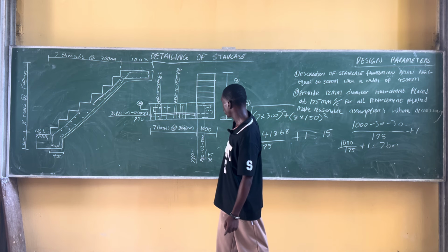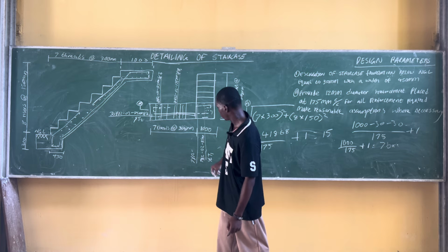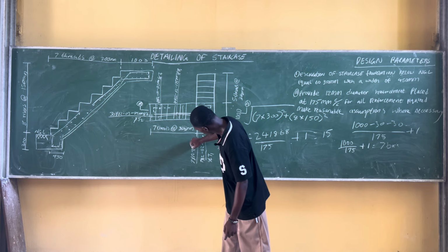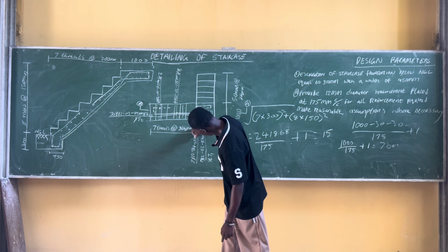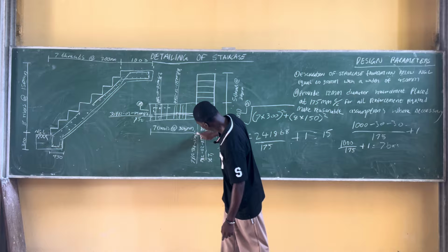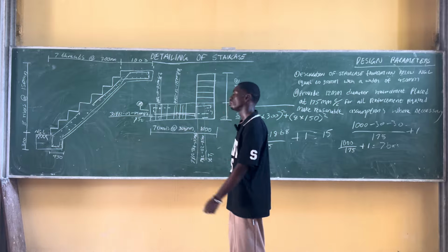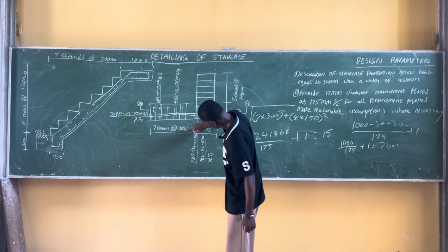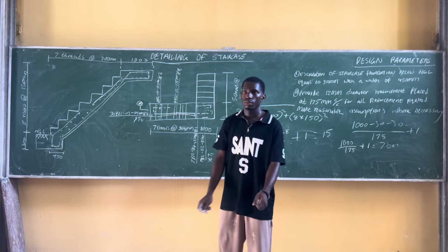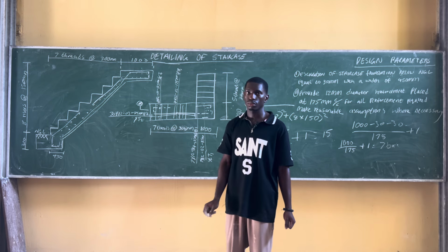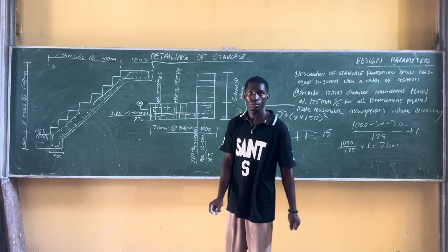And it cut. So I'll put here bar mark 4 at 175 mm center to center. B1. You understand? Okay, move.